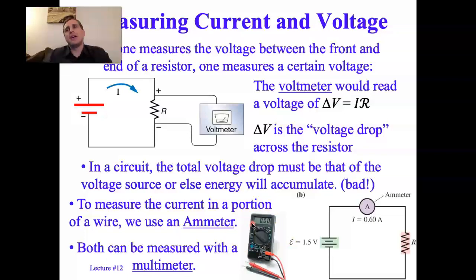And then back it off to more fine measurements if you're not getting a very large reading on here. Because always better to be safe than to overload the ammeter too soon. Okay.